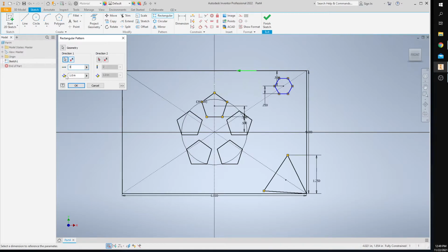So now this part here is saying how far apart they should be. Again, 1 inch apart is a little bit too much. So let's type in 0.5 and see the preview. That looks like a lot less, right? Because they're crossing over. So let's type in 0.7. Maybe that could be in the middle. Yep, that looks good, right? And we're still not finished.